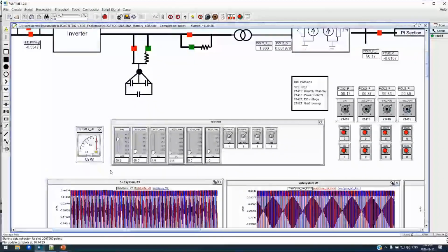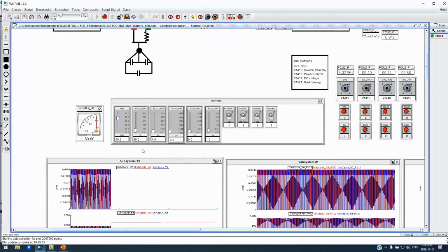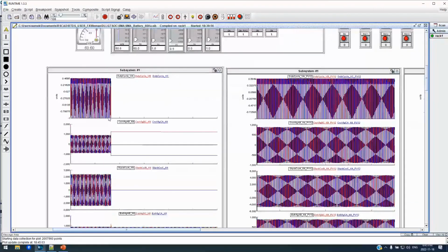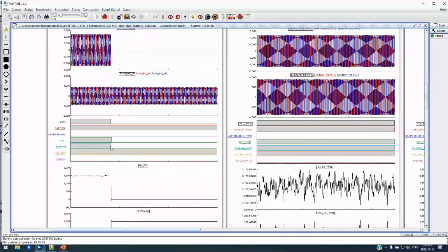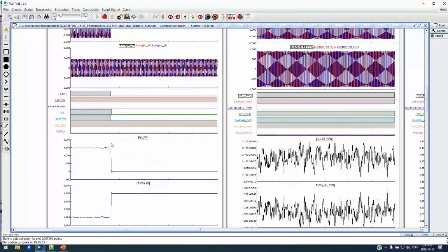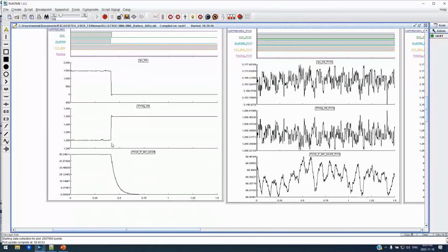It's still not tripping. But once I go past that, so I go to 60.6, and it's a constant value, it should hit the time limit and so it should trip. So if I go to 60.6 and enable, you can see the power went down to 0. If we look at our circuit, the system tripped. You can see these breaker signals tripped. So just as we expected.